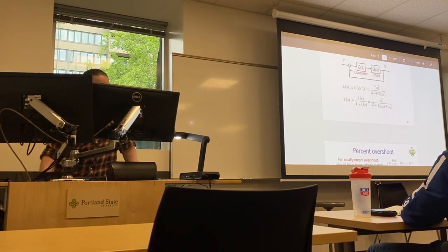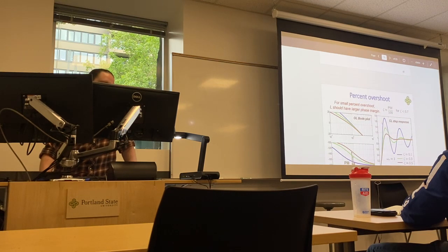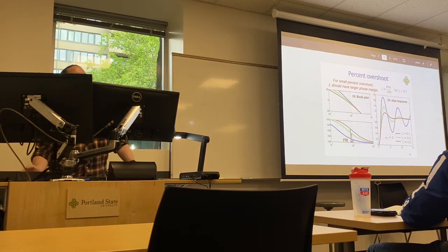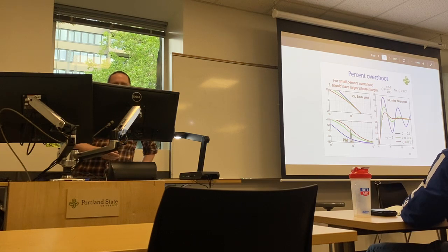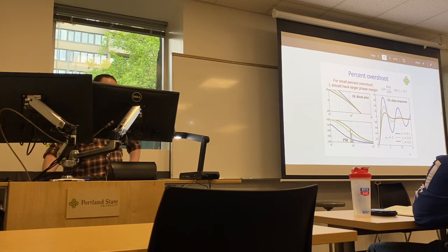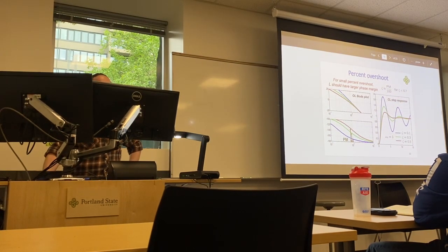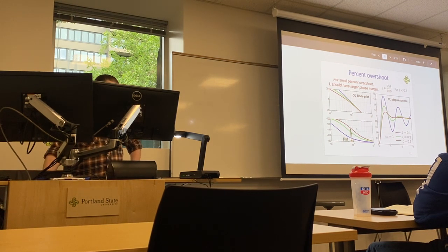So what we care about here, and while we're bringing this up, is in this transient overshoot. I mean, we covered it a little bit previously with our time response, but you can see how the damping ratio can help affect our closed loop step response. But you can also see from some of these additional plots how the change in our damping ratio can change our open loop Bode plot for the magnitude response and for the phase response.